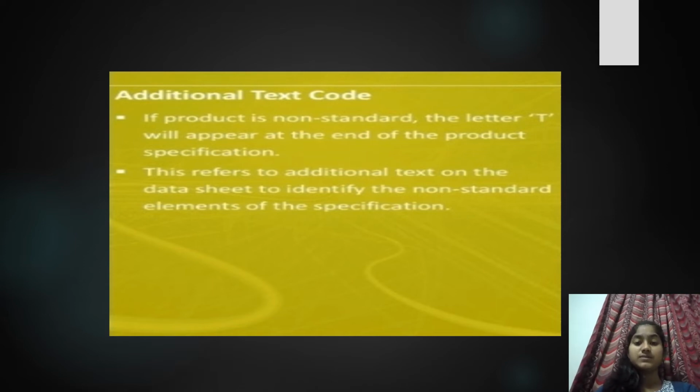Narrowband PLLs. In another application, VCXOs can be used in narrowband phase locked loops where only a small amount of frequency variation is required. Here, they are able to provide very good levels of phase noise. They may be used for signal reconstitution in this role.